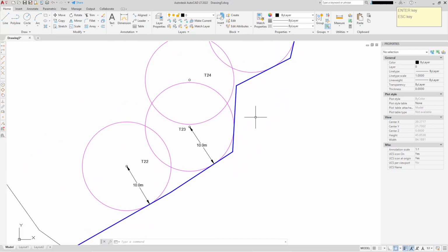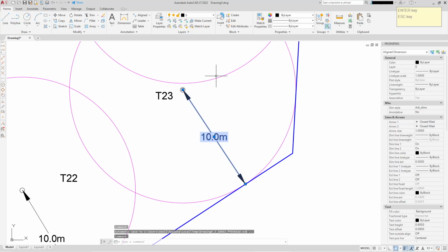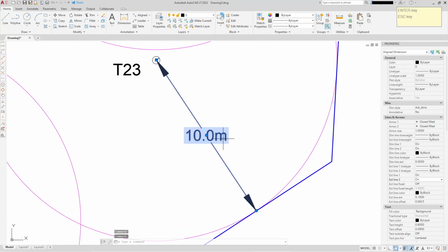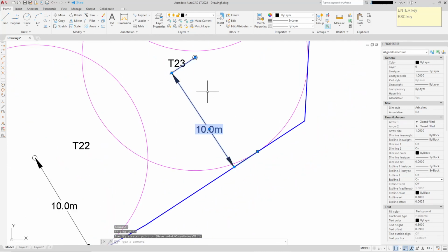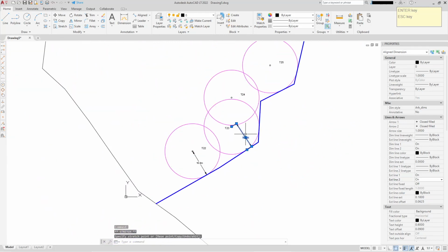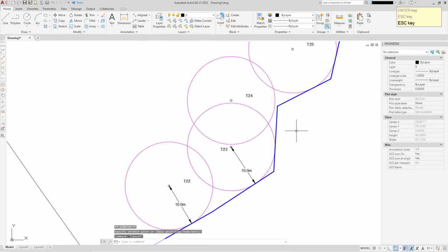Now I mentioned that I suppressed the extension lines. The extension lines are 2 lines that come out if you want to pull this away from the center. If I switch the extension lines back on, it's now got 2 extension lines, and drag this. You can see the extension line there, and this one's hidden behind the fencing. But that can be handy in some situations to have them on, but normally you'd have them off.